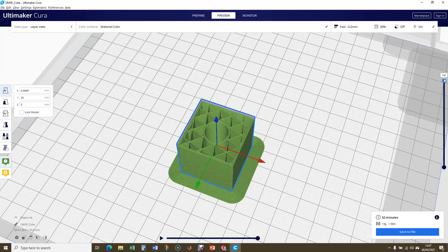At the top, then, it has to do a few solid layers on top of those triangles. So if we didn't have any material in there, if this was zero, we would now have no triangles in here. We'd have nothing to help support the top surface. So that's important, and that's why we do need to put some material in there in the form of a mesh.